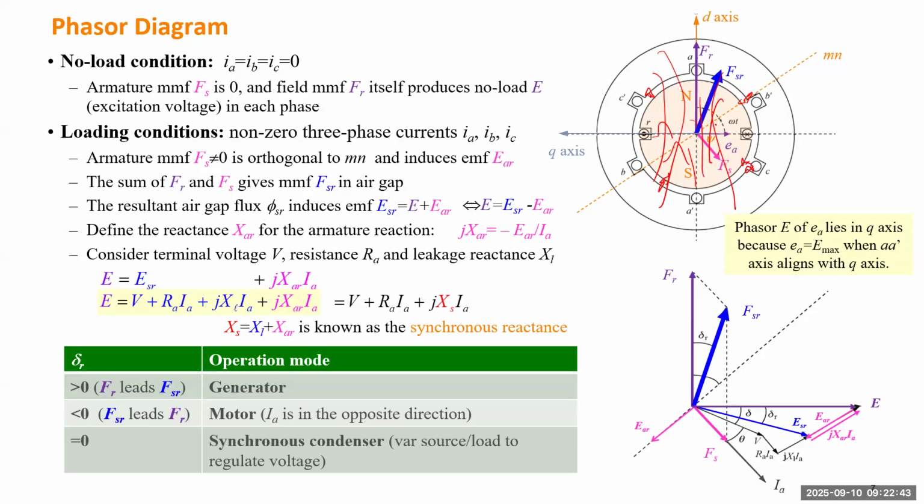Okay, so which means the flux in the air gap and inside of a rotor can be very different. And for this case, it's simpler because the rotor has a round shape. When it revolves, even though the spatial position of the rotor relative to the stator is changing, the magnetic field, the flux density, doesn't change too much. But for a salient pole rotor generator, that can be different, because in the quadrature direction, there will be more air gap. So the more air gap, the harder it is to build up the flux.